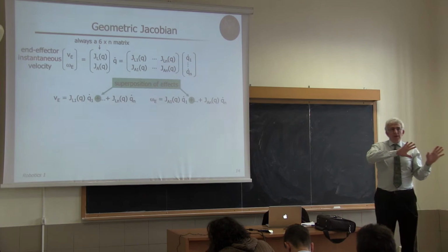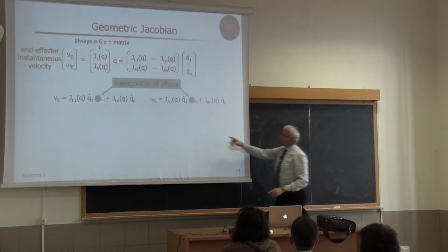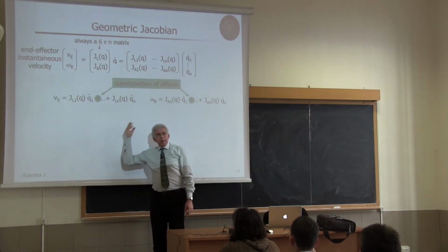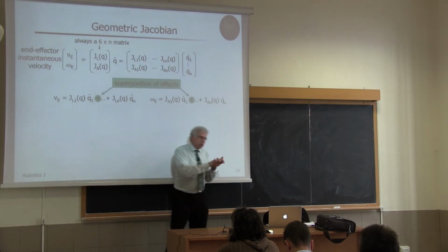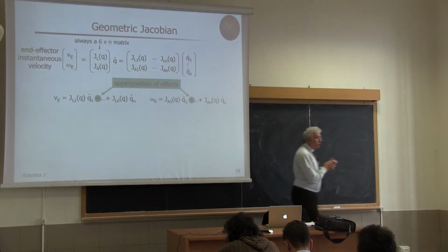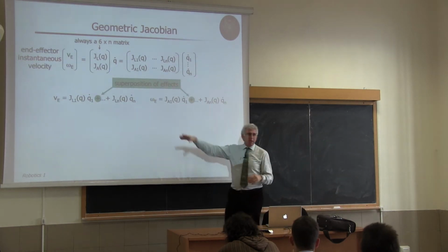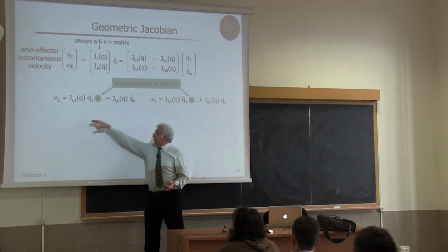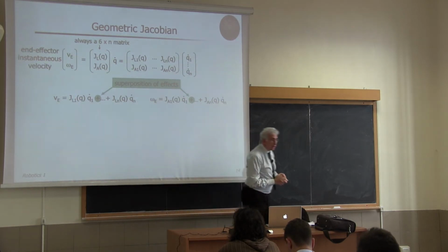So we just move one joint and look at its contribution both to the angular and to the linear velocity. If we are able to write this contribution in a generic form, and we will split two cases, if the joint is prismatic or if the joint is revolute, then we just repeat this for all possible joints and sum, and we have the expression both of the linear and angular velocity, but in between, by factoring out the joint velocity, also of the geometric Jacobian.